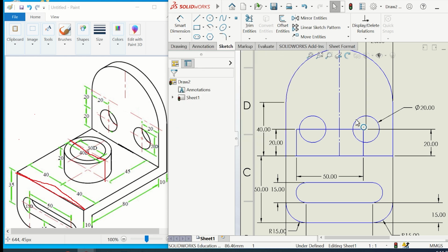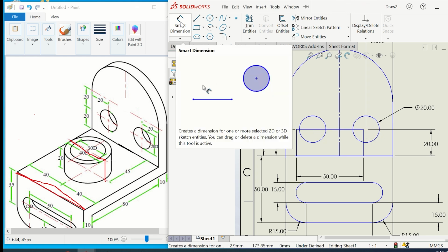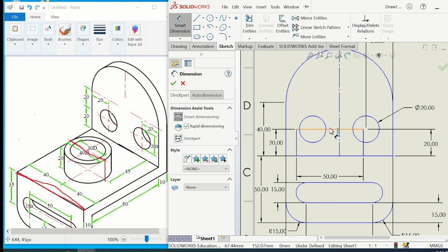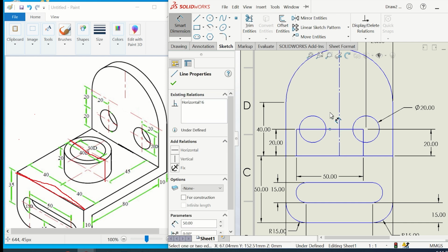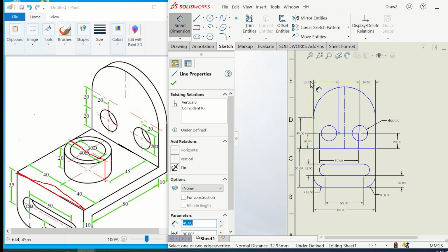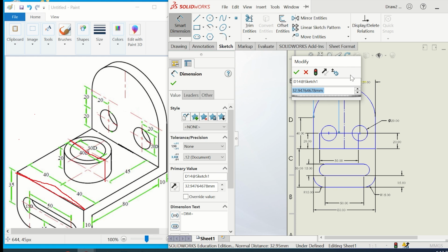It might end up being aligned with the center points of these two circles, but I'm gonna leave SolidWorks to do it if that's the case. So I'm gonna say Smart Dimension from the midpoint here, click to this edge here, and this must be 40 as we said.